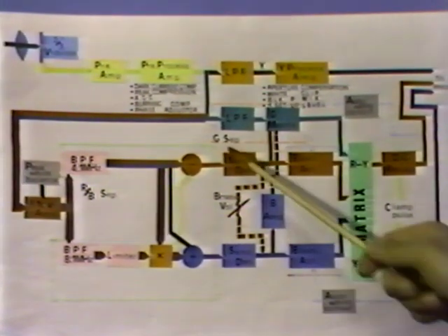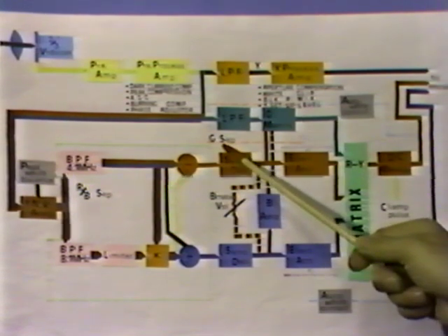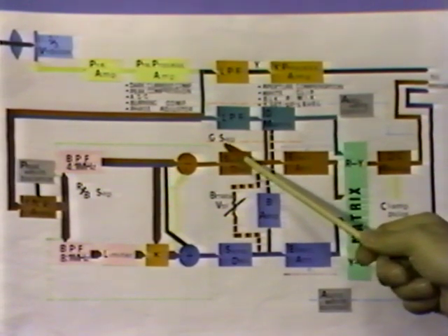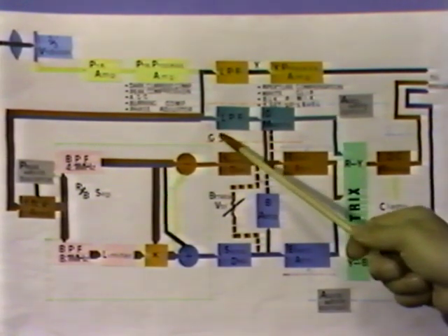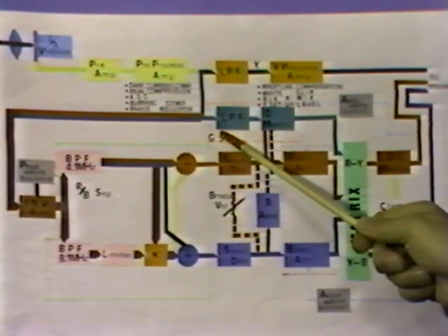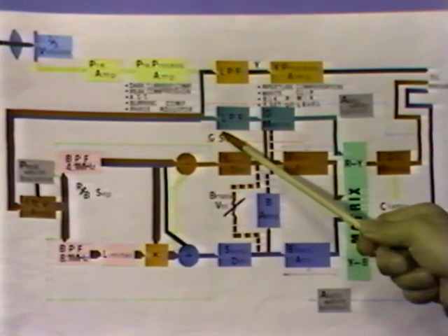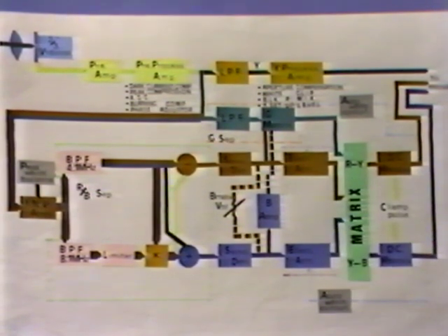The G signal separator is the mechanism to take out the low-frequency component, that is, the G signal, from the color multiplex signal. The low-pass filter only allows the low-frequency component of the color multiplex signal to go through, and its output signal is G plus 2/3 B and 1/3 R.